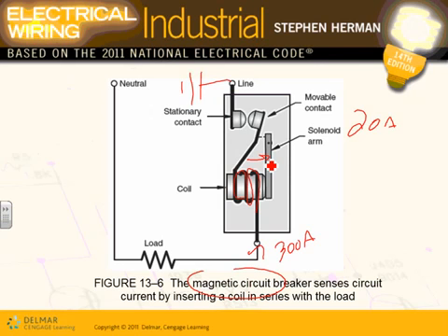So they open it like a magnetic starter, guys, with a coil. It energizes the coil, and the coil has a plunger or solenoid arm, and then pushes these contacts to open. So they use magnetism as a means of opening the circuit breaker instead of thermal. Does that make sense? Can you guys see how you energize the coil? It creates a magnetic force, pushes these contacts open. That's what happens inside that breaker if you have a short circuit.